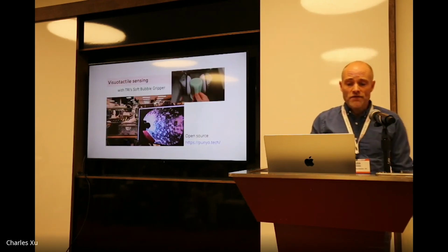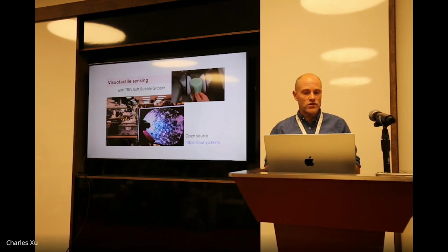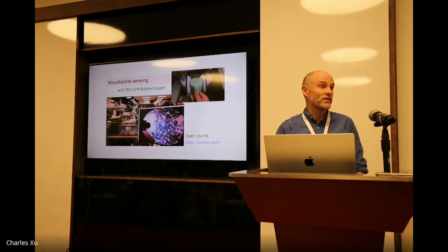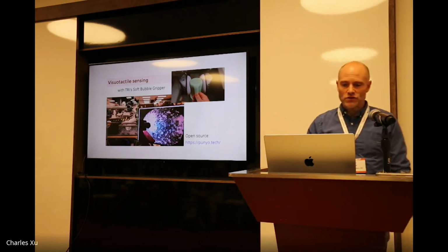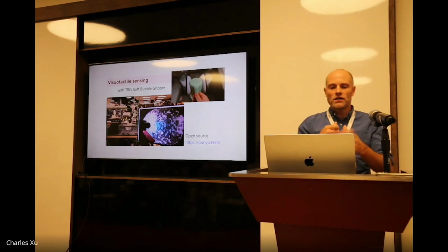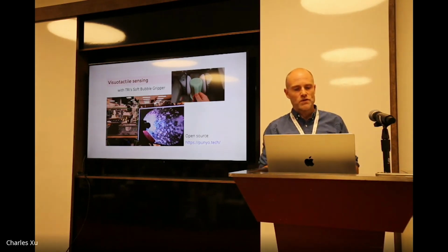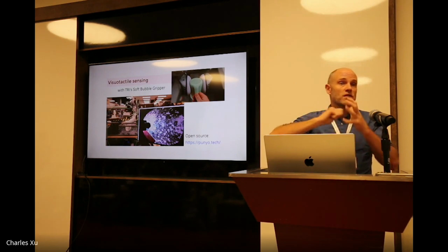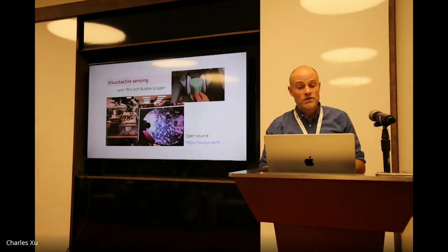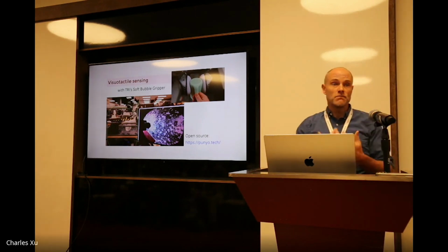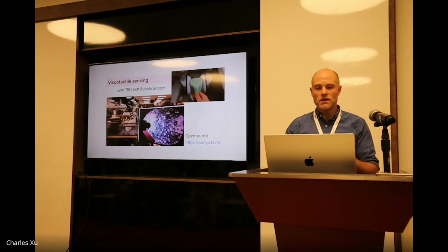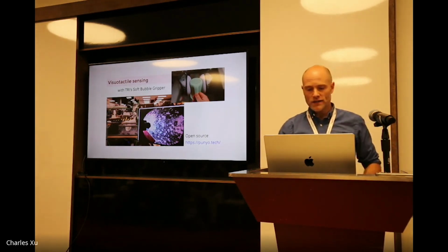Okay, and you'll notice that some of those demonstrations use visuotactile sensing. So that funny large bubble thing that you see, that's the TRI soft bubble gripper. Okay, there's a camera inside that. The deformations of the bubble correspond to the forces that the gripper's feeling, and even the stresses and strains that the gripper's feeling because of the patterning on the inside of the bubble. Okay, and some of those tasks were fundamentally more robust because of the visuotactile sensing. Maybe not surprisingly, but we wanted to be careful about evaluating that and seeing that.